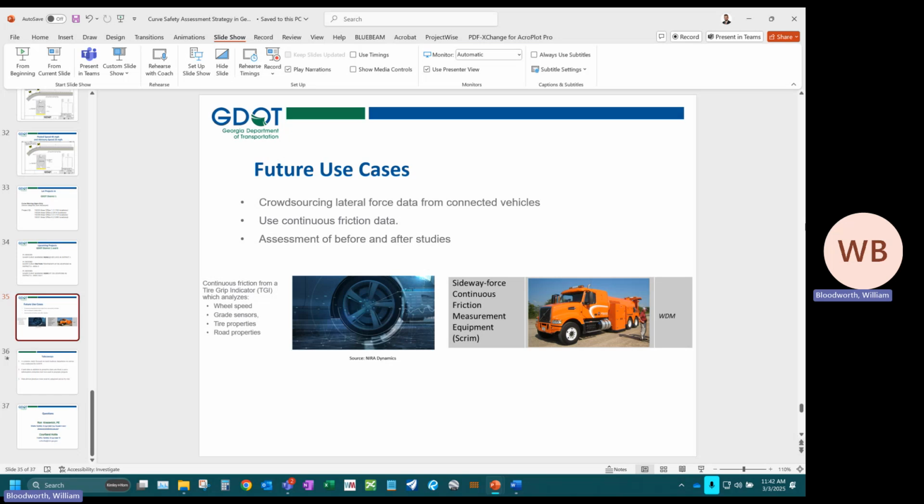Yes, I'm glad you asked. This is something that's new in the new MUTCD. It's called preemption supervision. This is something that's in the railroad track circuits. What this means is that if there's an error in the railroad track circuits, what typically happens now is it'll tell you that a train's coming. It'll drop the gates and the traffic signal will receive the signal and go into preemption. So you enter this situation where the lights and gates are flashing and the gates are down for extended periods of time when the train is not coming, and all the traffic signal knows is that a train is coming. That can be problematic for driver behavior.